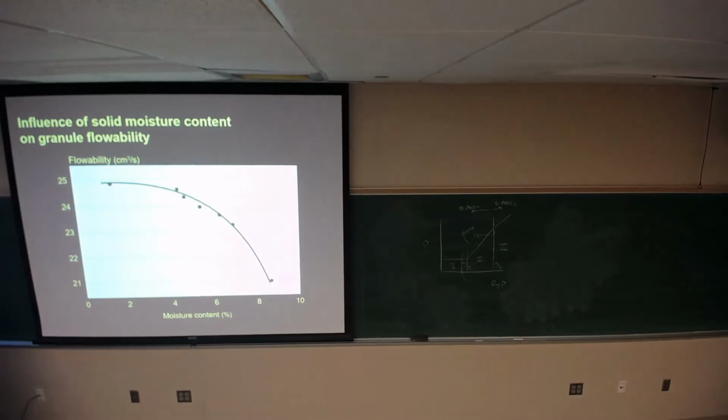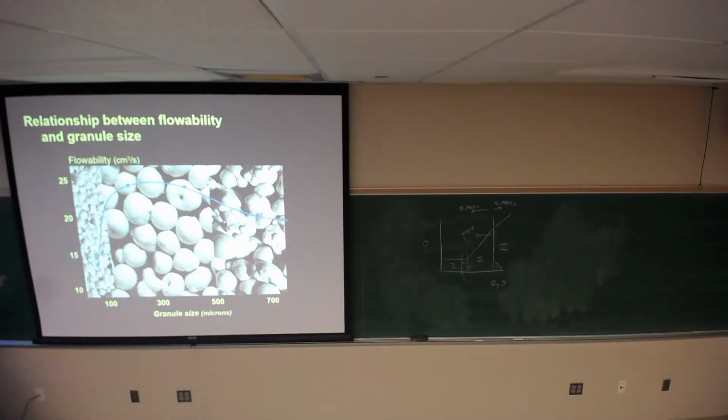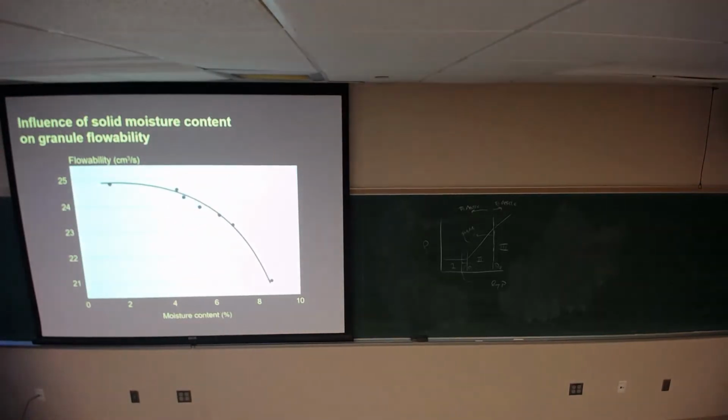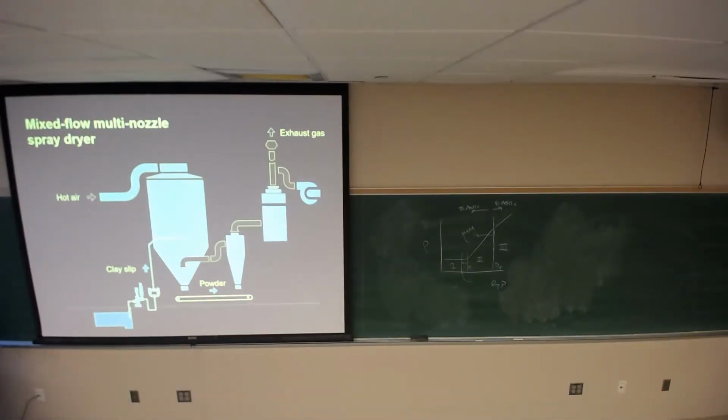here. Okay, this one, flowability, right? So you're looking for uniform flow, and you're also looking for uniform flow in terms of size. So they're very interested in those parameters. They do not care about much else. You need uniform flow. So first you got to have the right size. Second, you have to have the right moisture content. Okay. So the size is dictated by atomization and by materials such as viscosity of suspension, etc. Okay. And your flow is dictated by water content.